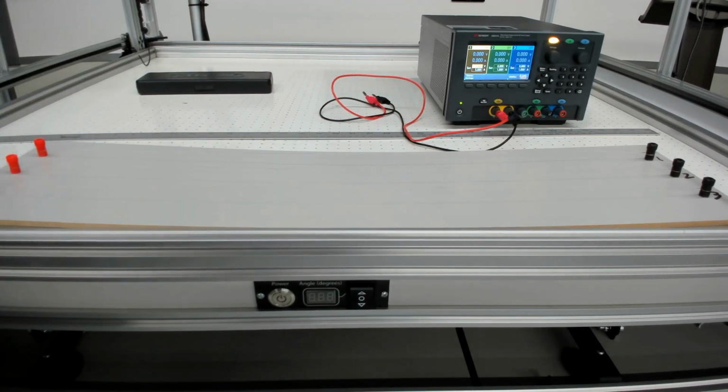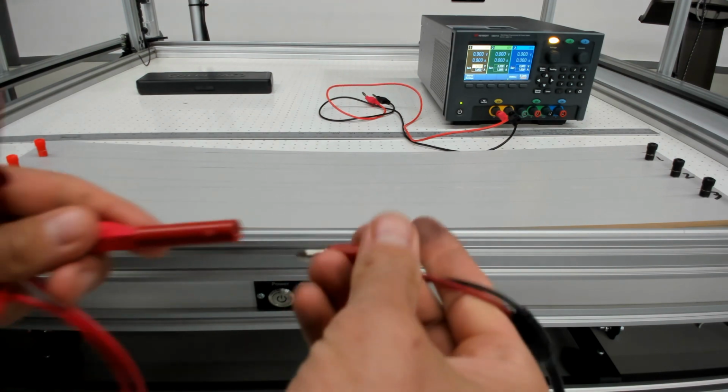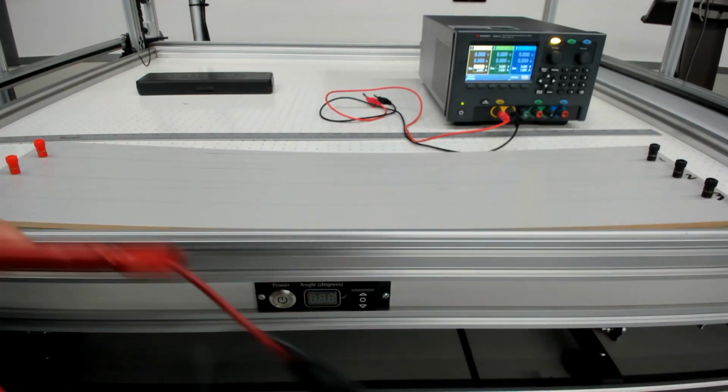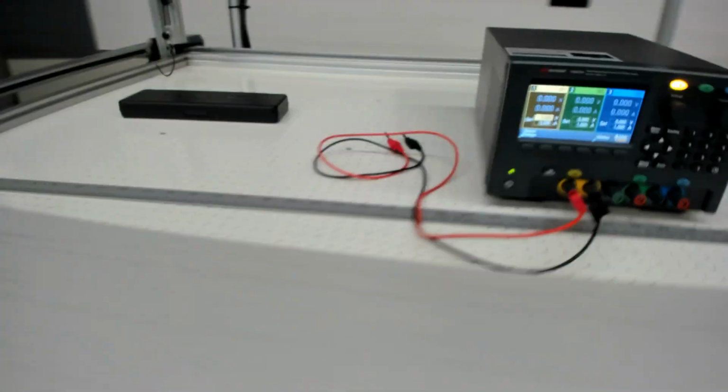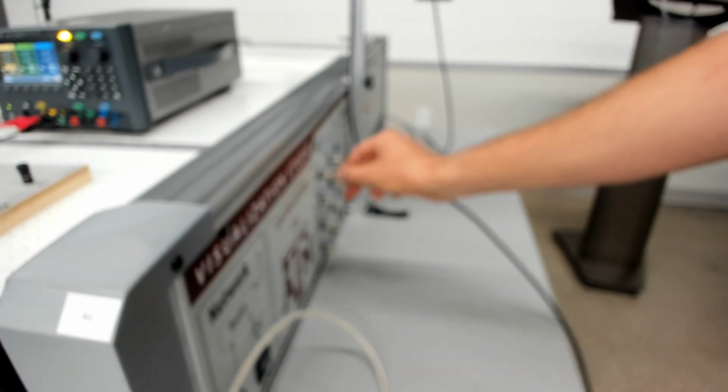So we're going to take these 2 cables, our BNC to banana and our test clip, hook the test clip up to the BNC to banana, and then we will come over and attach that to the DAC. For our purposes here today, we'll just hook this up to channel 0, and set the cable up there till we're ready for that later on in the lab.